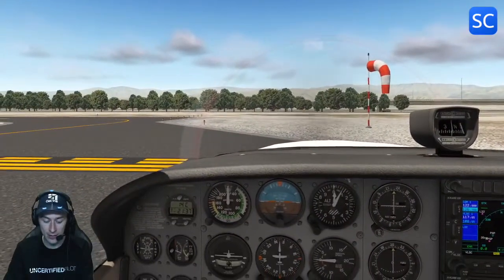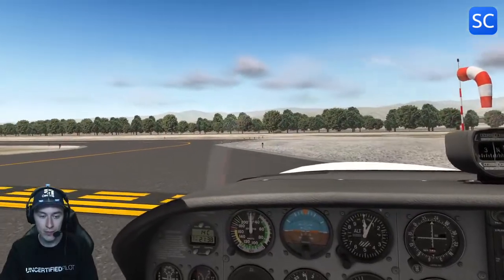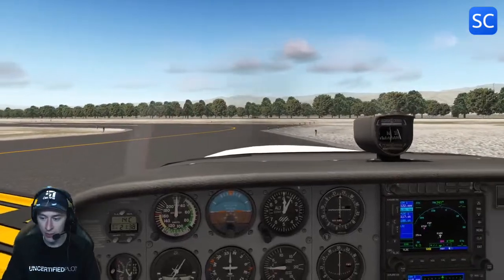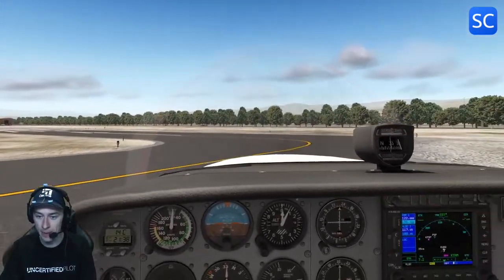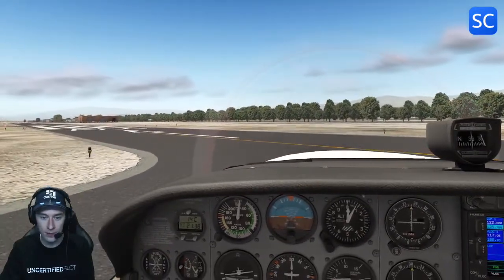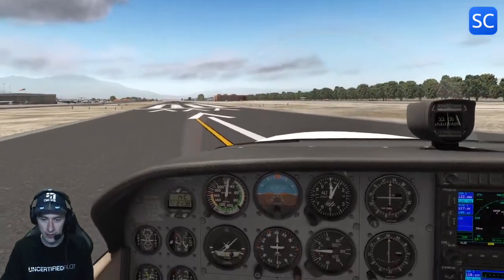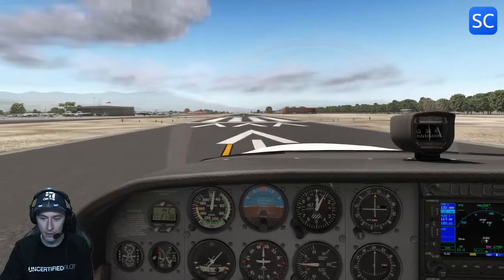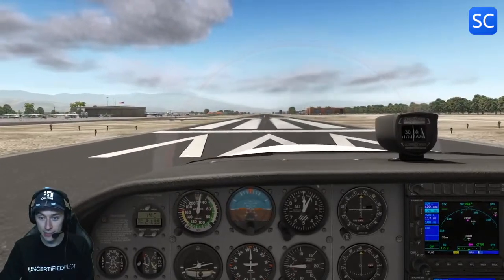Let's go, guys. Landing lights on, strobe lights on. There we go. Bermuda Dunes traffic, Skyhawk Papa Hotel Tango Andy Mike is departing runway 28 for a left downwind departure. Bermuda Dunes. There we go. There's the runway, line up. Again, fully lit up. Corresponds with our heading indicator, and let's go, guys, full power.